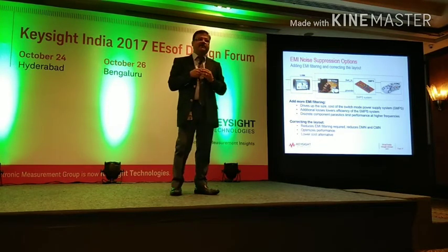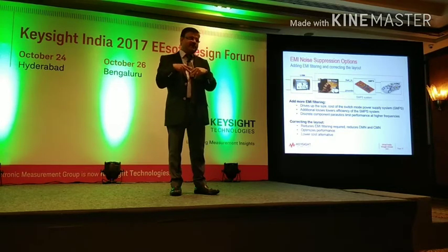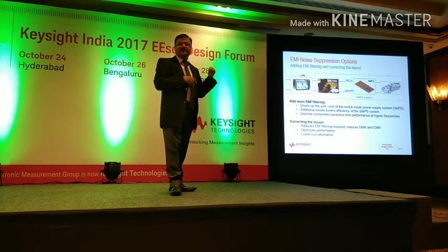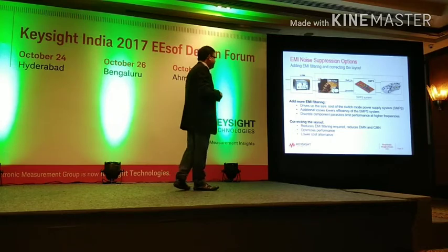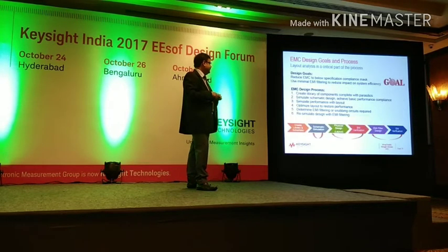Say, what about EMI filter? But EMI filters are bulky, costly, and then remember, differential mode noise and common mode noise will require different types of filtering. So you first need to understand for what purpose you are doing it. So you cannot just have EMI filters all over the place in your system. That's not the way. And it's also costly. They're not very cheap. Okay.